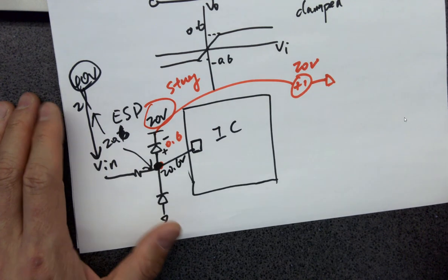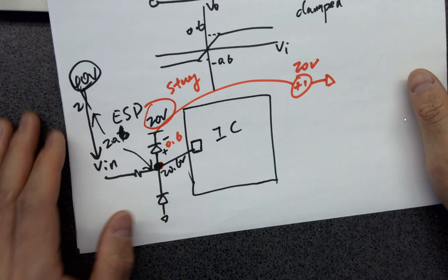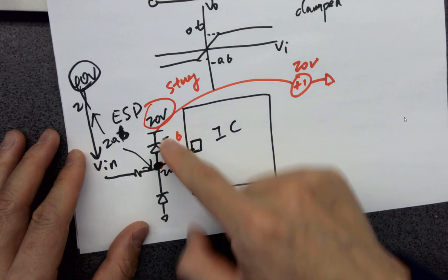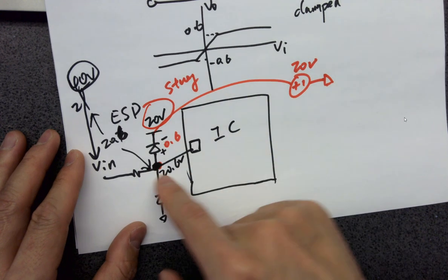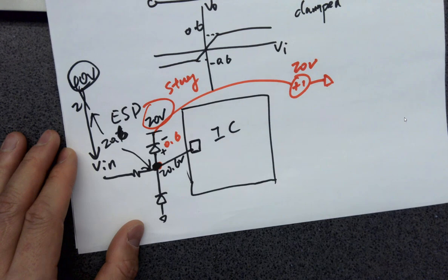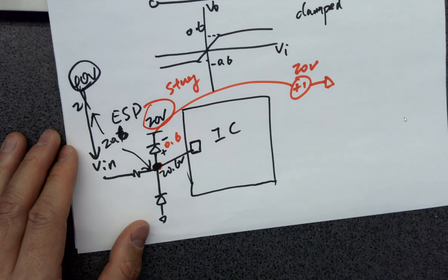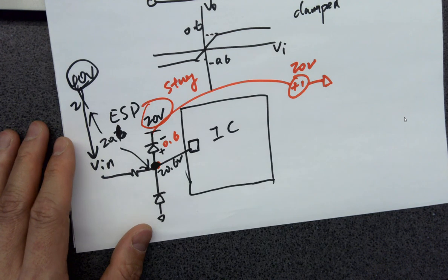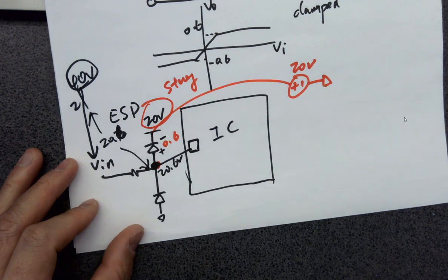How is that possible? I got a 40 volts surge for V in accidentally, and eventually, because you have this circuit, this point will never be larger than 20.6 volts. It's protecting the IC over here. Why does that work? Where's the current? Where's the voltage going? How did I remove the surge with this circuit?